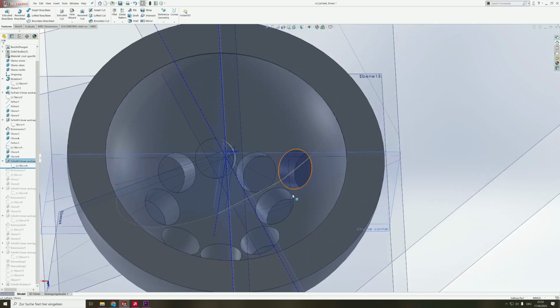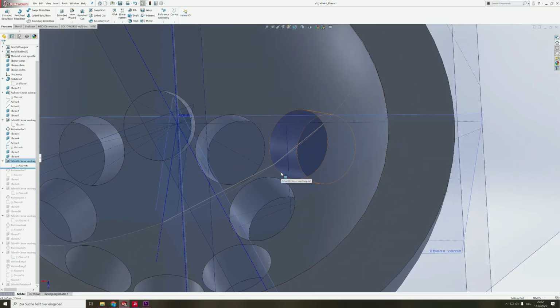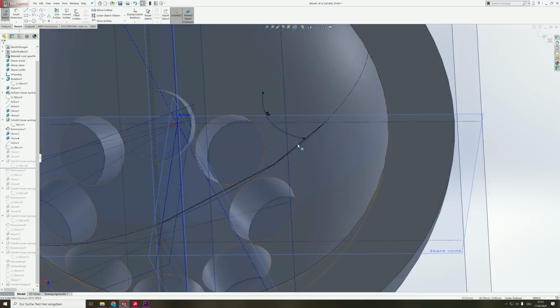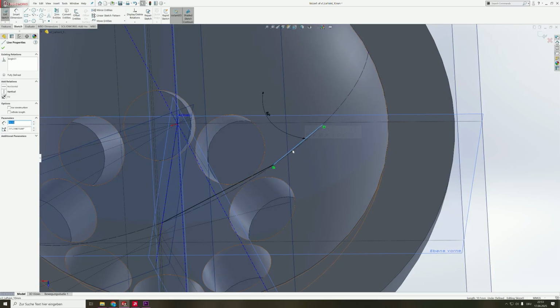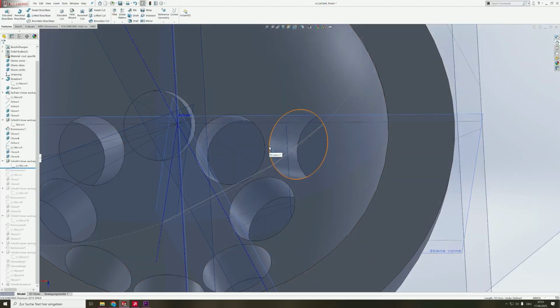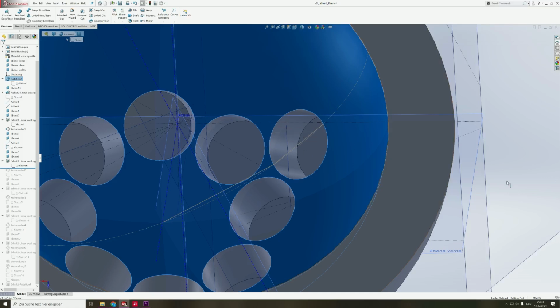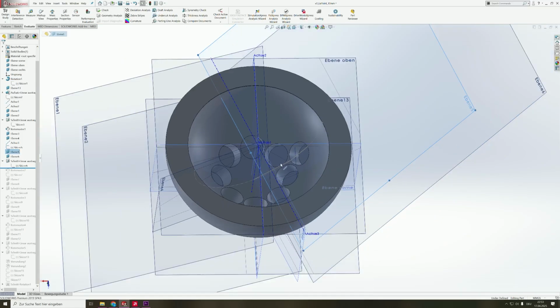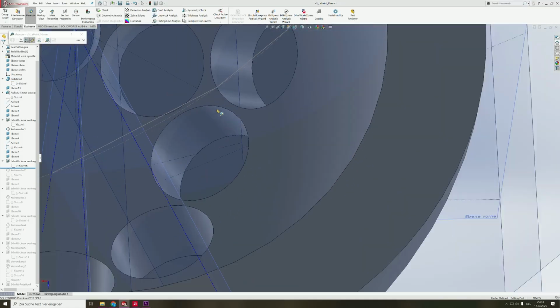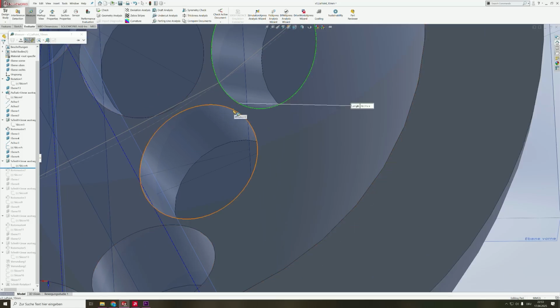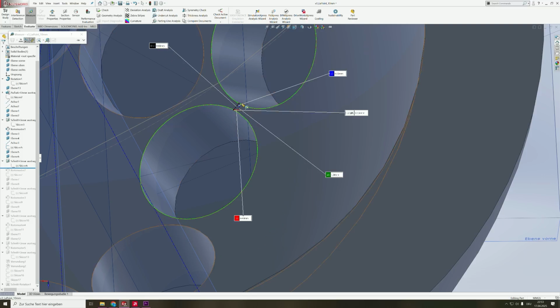And now we come to the positioning part again, where you should place this line. I showed you this again on how to determine where you should place it. So this is always a bit of trial and error. The reason for that is with 3D printing you have to have a certain distance. I will just quickly show you this. Between the holes you have to have a certain distance because otherwise the print won't turn out that fine. And as you can see here we have 0.68 millimeters distance, which is just enough to make the 3D print possible.